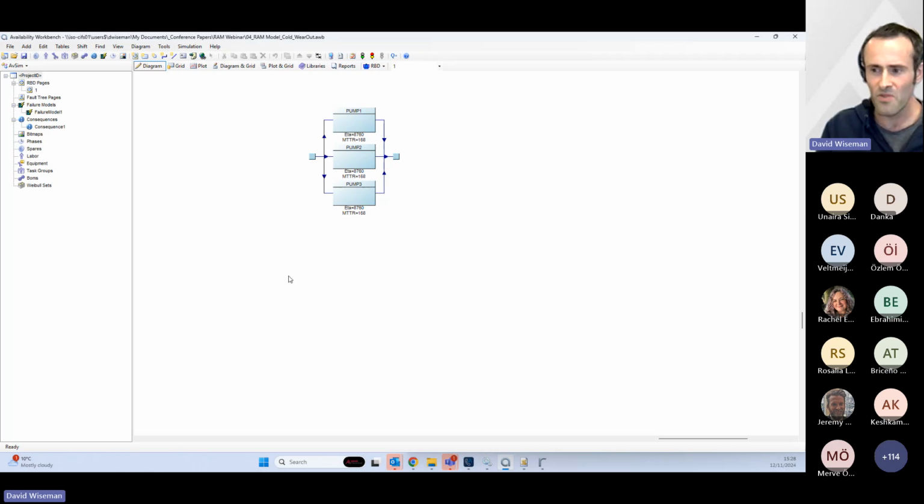For anyone more familiar with mean time to failure, failure rate is just the reciprocal of mean time to failure, 1/MTTF. But it's a measure of basically how often a first time failure will occur in a component. So in a fault tree and a conventional RBD, we generally assume that the failure rate, that the mean time to failure, if you prefer, is constant.